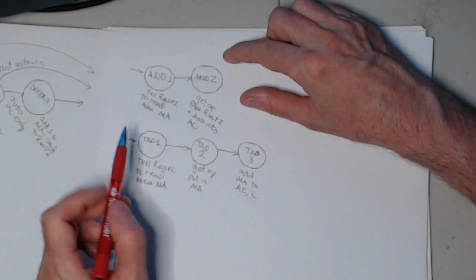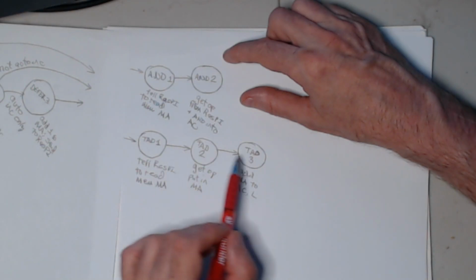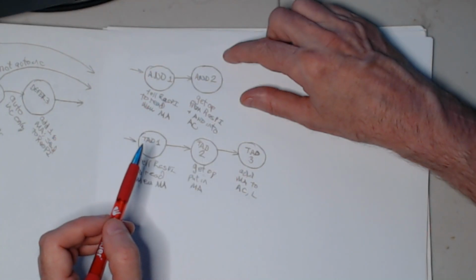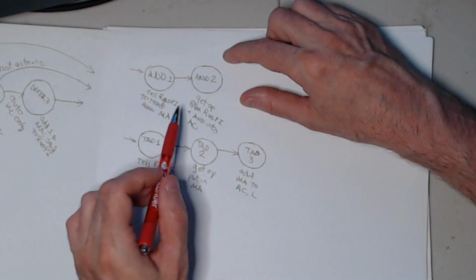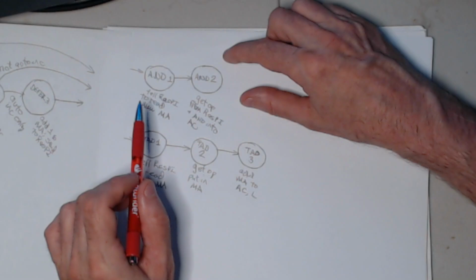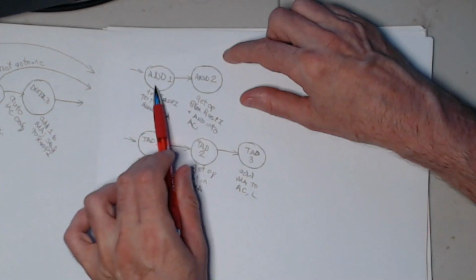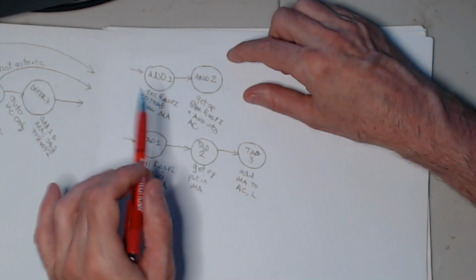So what this processor will do to save time for the common case of doing a TAD that follows a DCA, or anytime the accumulator is 0 and you do a TAD, is it pretends it's an AND instruction and the accumulator is all ones. It will do these 2 cycles here for an AND instruction, just as a little optimization to speed it up a little bit.